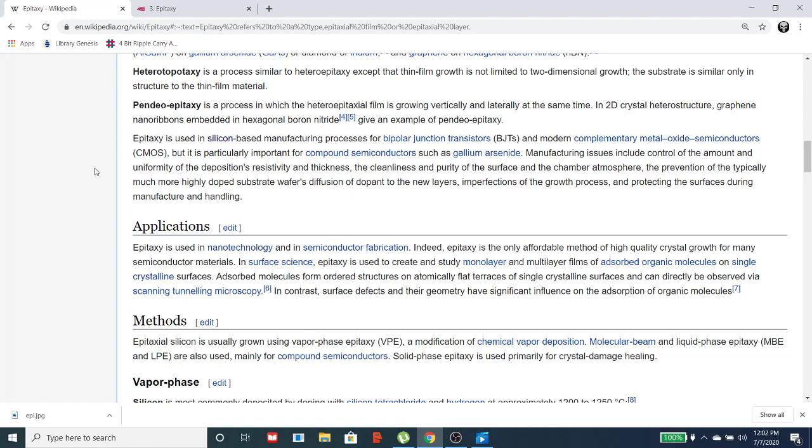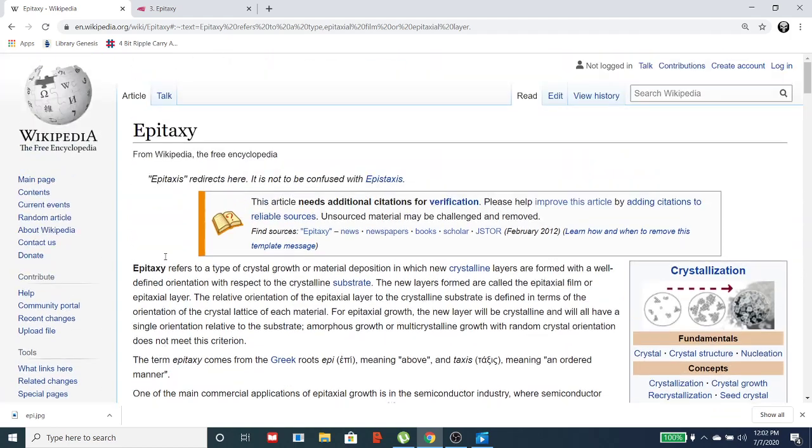We will learn about all these things, but first we're going to talk about what we covered in the previous lecture. We covered silicon, how silicon is grown from a crystal growth through the Czochralski process, and how we extracted silicon from silica. That is the most important thing, the chemical reaction that we talked about. Then we talked about the different kinds of defects in silicon. We talked about point defects, area defects, dislocations and all those things.